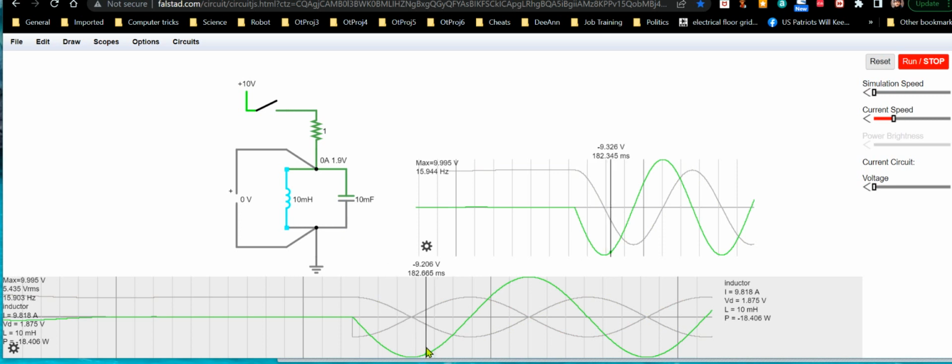Okay, but then the capacitor is master at that point, so it's the source of voltage in the circuit, not the inductor anymore, and that's what basically charges up the inductor. It's trying to resist its current increasing now, but in the process of resisting it, it's making its voltage slightly lower than the capacitor's voltage, so it's actually absorbing energy from the capacitor, and as long as that's happening, the capacitor can't do anything other than discharge itself.